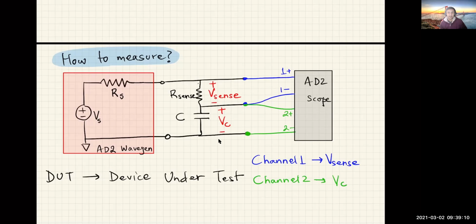even though you don't have an 82, right? So the instructions in the LT-SPICE version of the tasks tell you specifically to measure the voltage across the resistor and calculate the current. So just do that and don't take the shortcut route of directly measuring the current. If you would like, you can confirm your answer by making current measurements. But to start off with, just follow the same steps that we would do with an actual circuit and actual equipment.